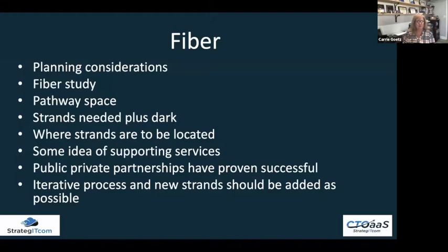As you start turning up new services and new cool services come along, and you want to add a little of that and a little of that, you start filling up some of those things. We can do different things with wave division multiplexing and other things to help take advantage of all that we have in fiber. And some of the fiber, to be fair, is really old fiber that just won't support the newer protocols and newer technology. So it is important to check the fiber and see what you have and make sure that the fiber is going to support it.